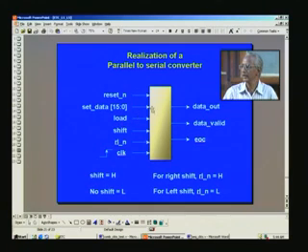And once you have loaded, you have one more control called shift control, because together with that you have a right or left shift available. Basically it is a shift register, that is why we use this. All this shifting will happen only at the positive edge of the clock, and out comes single bit data, because that is what we want, parallel to serial.